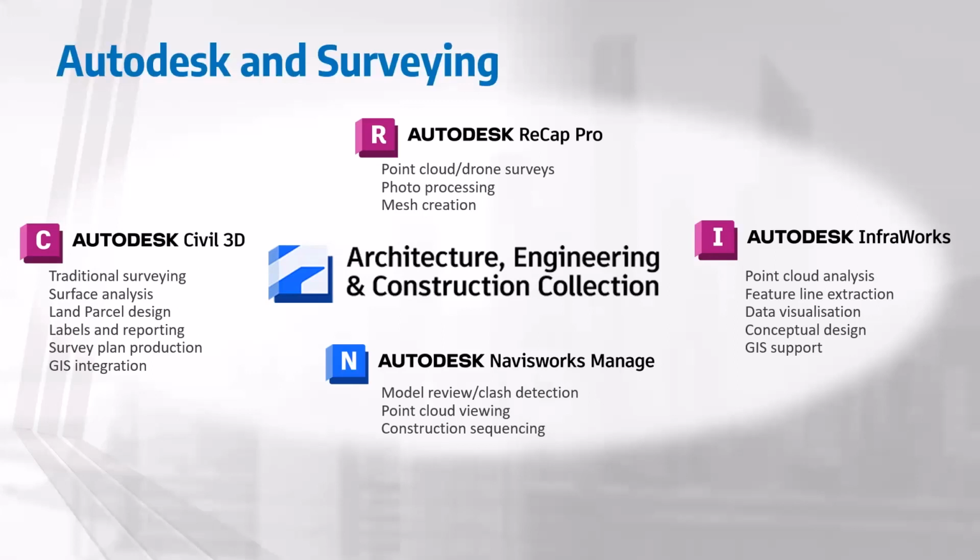On the surveying front, Infraworks is actually a place where you can intelligently assess that point cloud. You can do linear feature extraction, vertical extraction for cars and trees and signs and all that sort of stuff, and basically provide to whoever you're handing off your survey data to some information about that cloud. You know, the decision about what is a break line, what is a main feature, what is the key information. So Jack will touch on that as well.